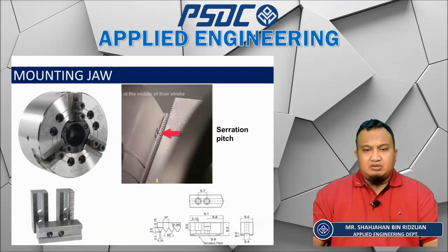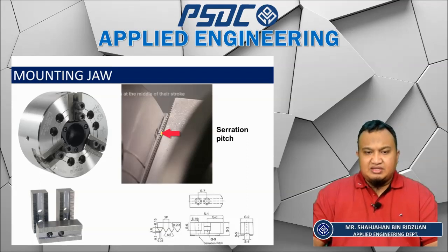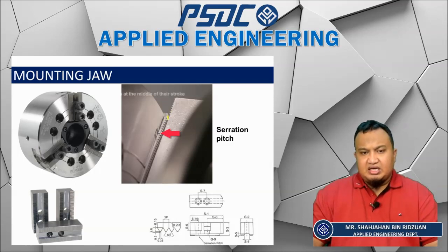And mounting the jaw is a very serious part that you need to pay much attention to. So in this matter, you need to check the serration pitch on the jaw and on the chuck when you clamp the jaw to the chuck.